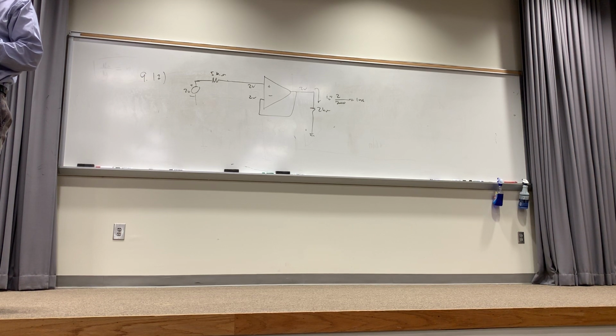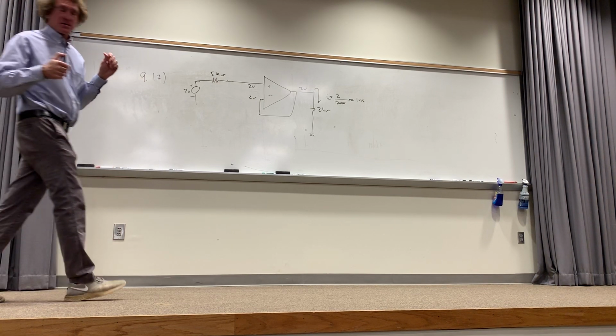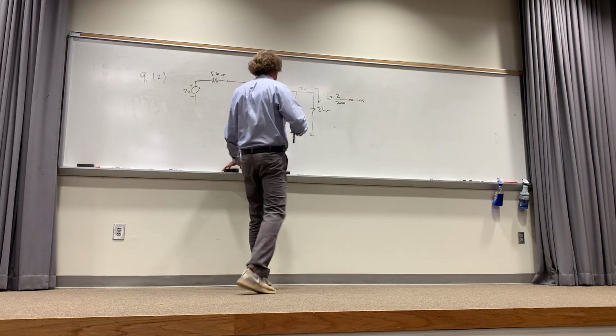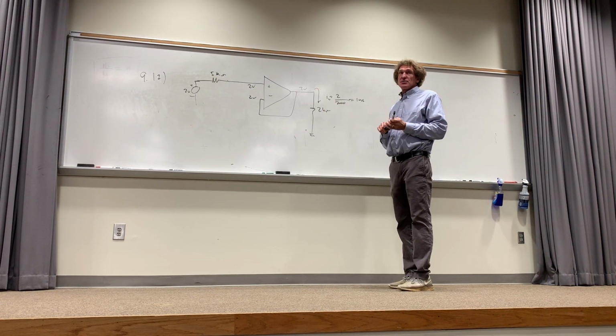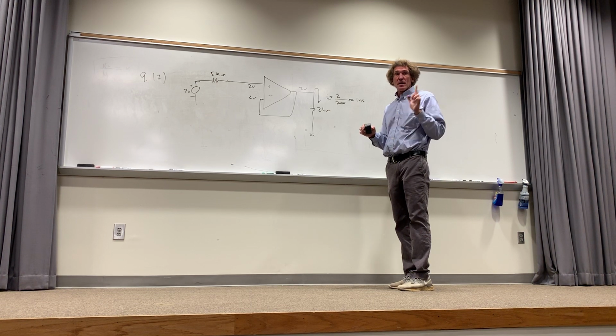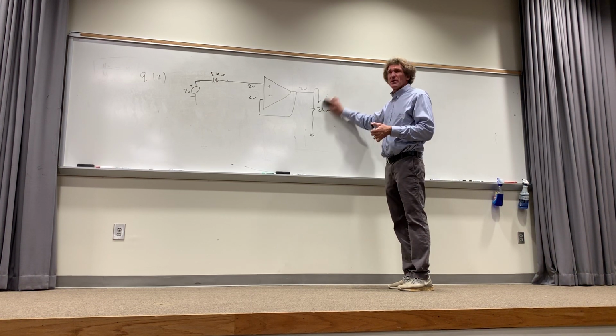It's used all the time. Whenever you have a high impedance associated with any kind of sensor, and you need to measure that voltage, remember this follower circuit. They're very useful all the time. You don't want to just amplify the heck out of it. You want to do this first, because this will get you what you need. All right. Now, next, another one.